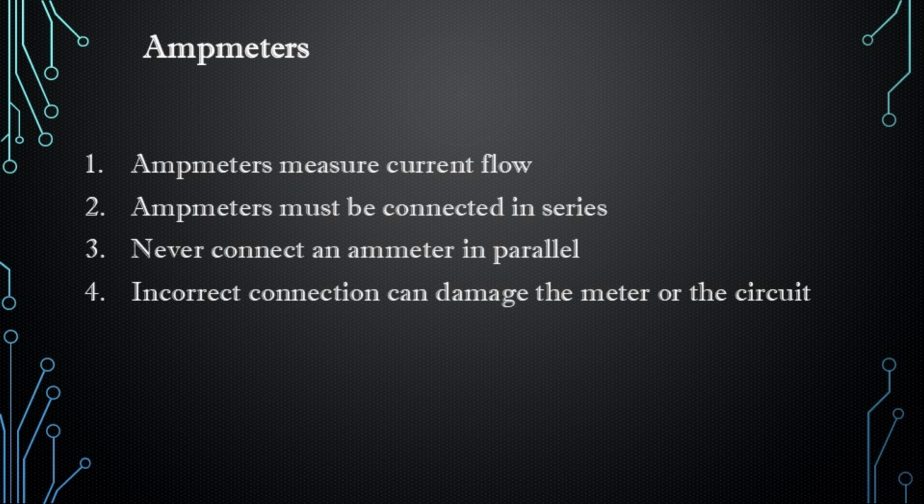An amp meter must be connected in series. That is a hard rule. The current has to pass through the meter for the meter to measure it. That means an amp meter is inserted into the circuit path. It is not laid across the circuit the way a voltmeter is, and this is where students can get into trouble.